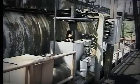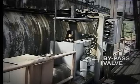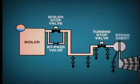To overcome this problem, 1 or 2 small bypass valves are fitted, say 1 inch in diameter. Due to the much smaller face of this valve, it can be opened to allow steam to enter the main steam line. Initially, this steam line will be cold and the steam will obviously condense. This condensate must be removed through the drain lines, which are fitted at low points on the line, including just before the turbine stop valve.